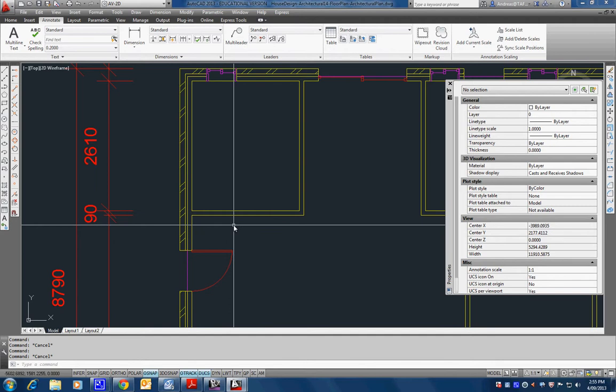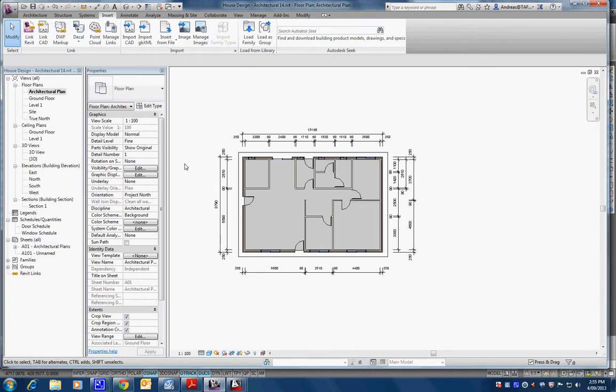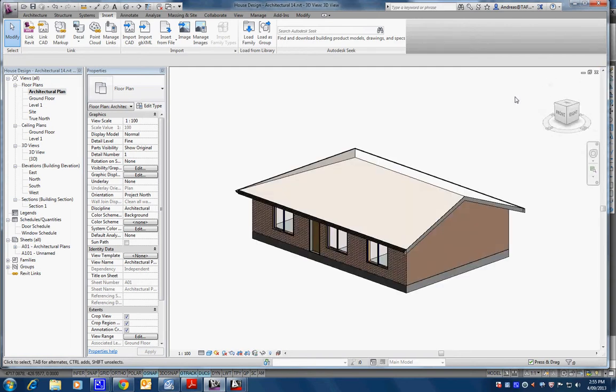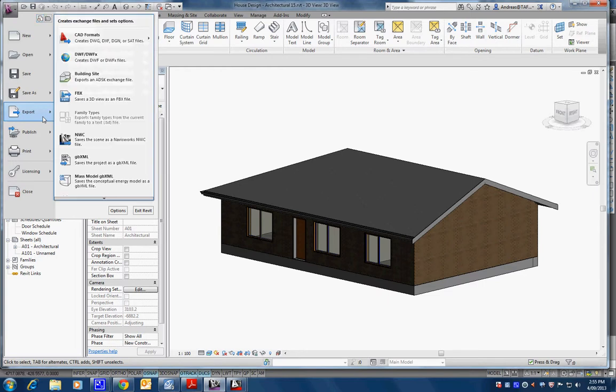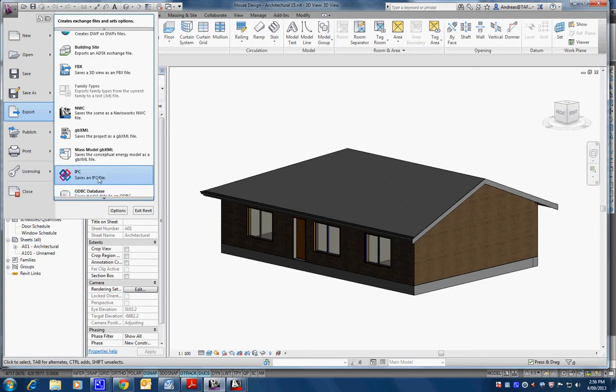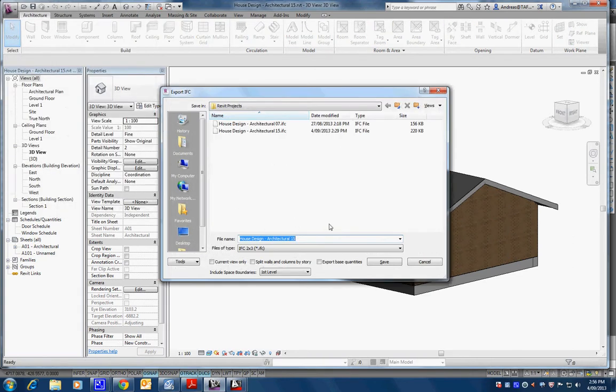If we quickly go back to this, hopefully we won't run out of time, because now we've lost our time. We're looking for 15 up here. If I export this to IFC, I go down here, export. IFC is always hiding. It's down the bottom here. There it is. Industry Foundation Classes, which is basically the XREF equivalent, a common format for exchanging between all BIM software.